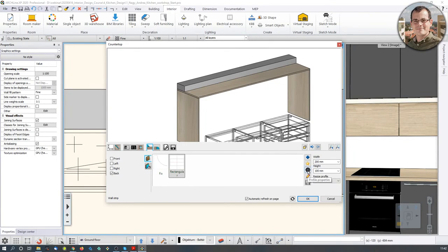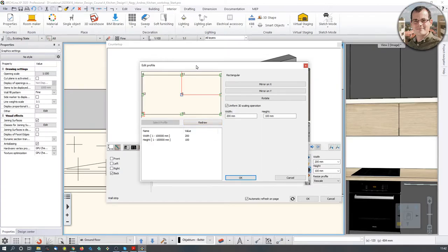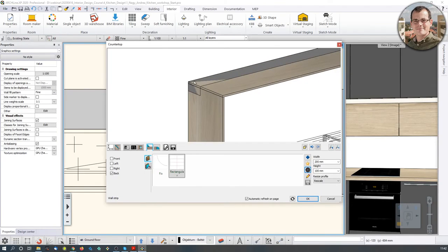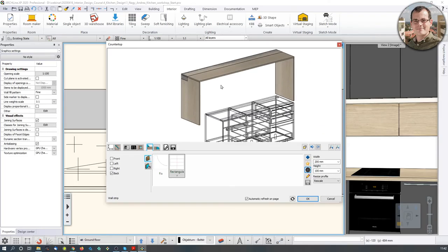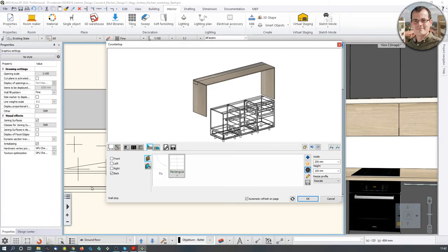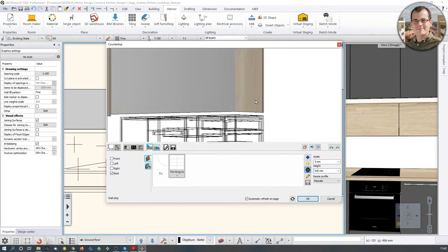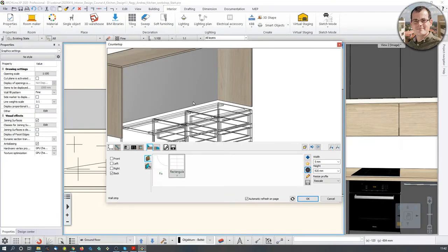First, we go to this cogwheel icon, and we remove the position of the reference line, because once the reference line is kept here, then the Backsplash is always going to add it to the top of this unit, but I want to move it to the top left corner, because if I do, this element is going to be pushed inside. So far that's good. The width and height we have to change. The width should be 5 millimeters, and the height should be 920 millimeters. And when I do that, now the box is almost complete.